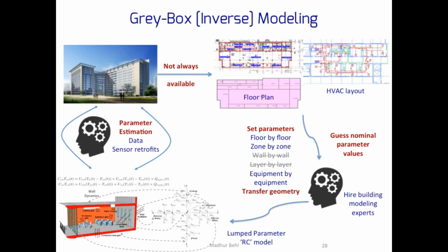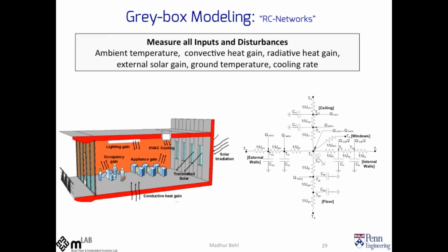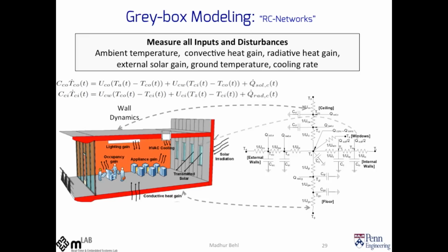So broadly speaking, the way this would work is that for a given zone, and every room in the building, you would first account for the different thermal disturbances that can affect the temperature and the electricity consumption of that zone. And for different surfaces, you will use thermodynamical equations and model each surface as a different branch of that RC network, where the R and the C coefficients are, again, the thermal coefficients rather than the electrical coefficients.